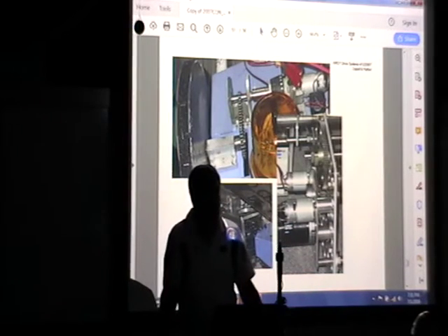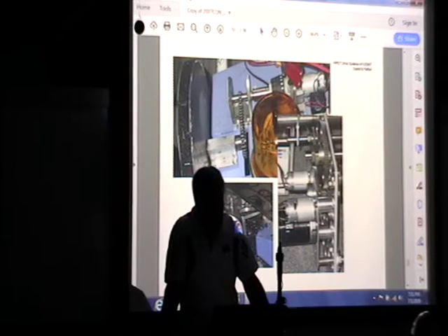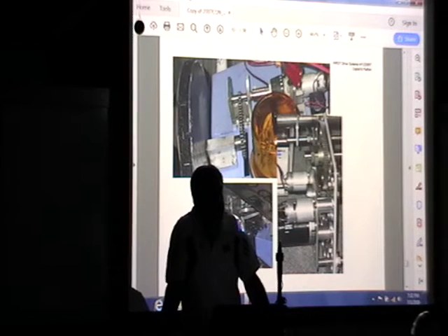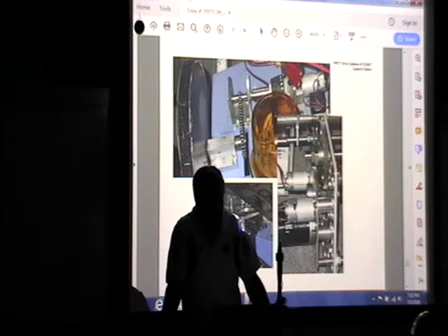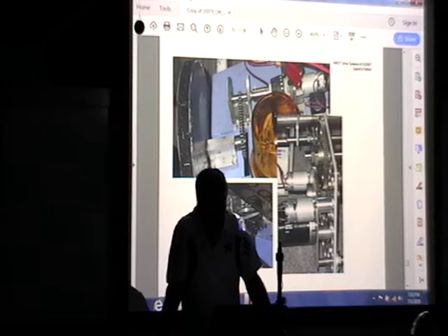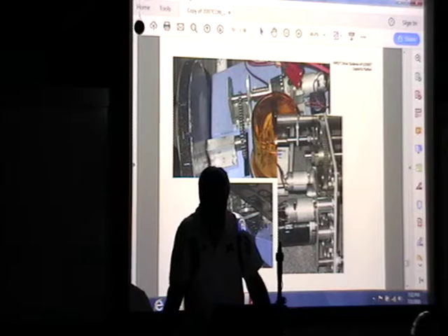Zach? Is it still a major problem if you're having the parts printed by like a laser cutter, or can you trust the laser cutter that it's gonna be accurate enough? That depends. A lot of times laser cut parts don't come into size. They certainly aren't sized for a pressed-in bearing, but when you start talking about flange bearings, they might be okay.